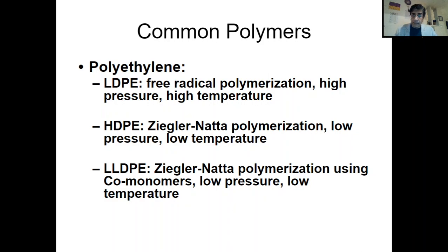So high density polyethylene is a purely linear polymer. Low density polyethylene is a branched polymer. It has several branches, longer size, smaller size. So what is this? Linear low density polyethylene. Linear low density polyethylene is also a linear polymer, but it has very short branches.